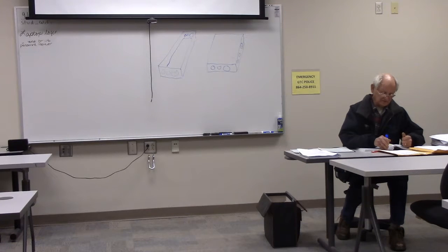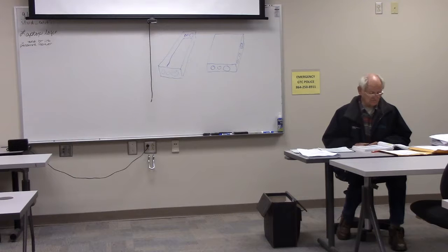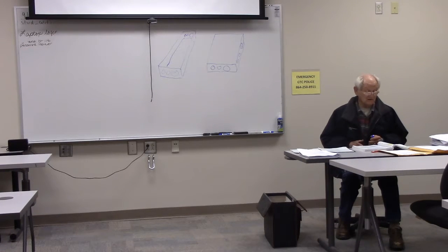Where angle or U-pulls are made, the distance between each raceway entry inside the box and the opposite wall of the box shall not be less than 6 times the trade diameter or metric designator of the largest raceway in a row. The distance shall be increased for additional entries by the amount of the sum of the trade diameter of all other raceway entries in the same row of the same wall of the box.